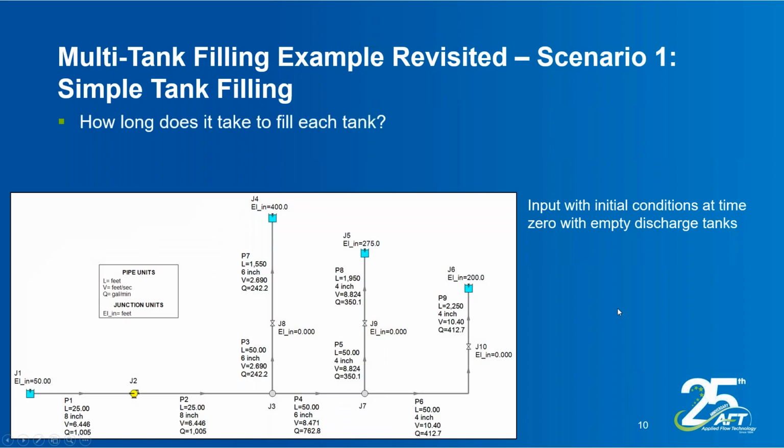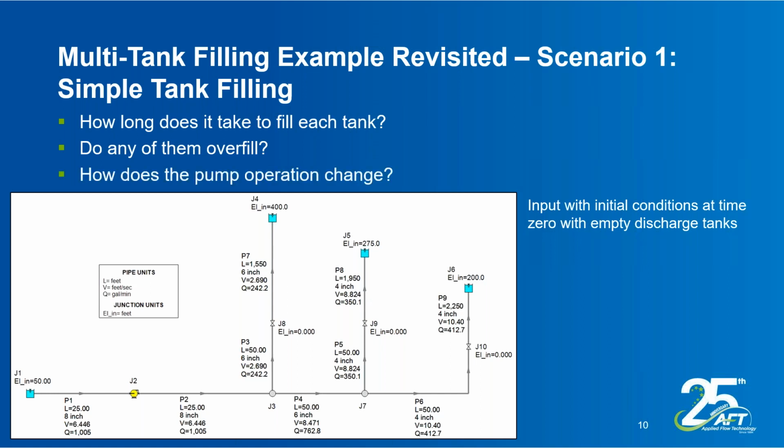And the questions that I want to ask: how long does it take to fill up each tank? Do any of the tanks overfill? Because that would be a major problem, especially if it's a corrosive fluid. But even if it's just water, you don't want a whole bunch of water flooding everywhere. And then finally, how does the pump operation change throughout the day? So that is scenario number 1.